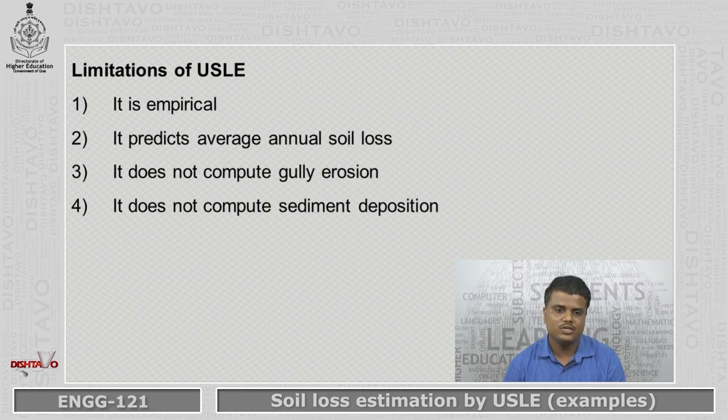Few limitations with this equation. It is an empirical equation. It predicts only average annual soil loss. It does not compute gully erosion. It is limited to only sheet and rill erosion. It does not compute sediment deposition also.